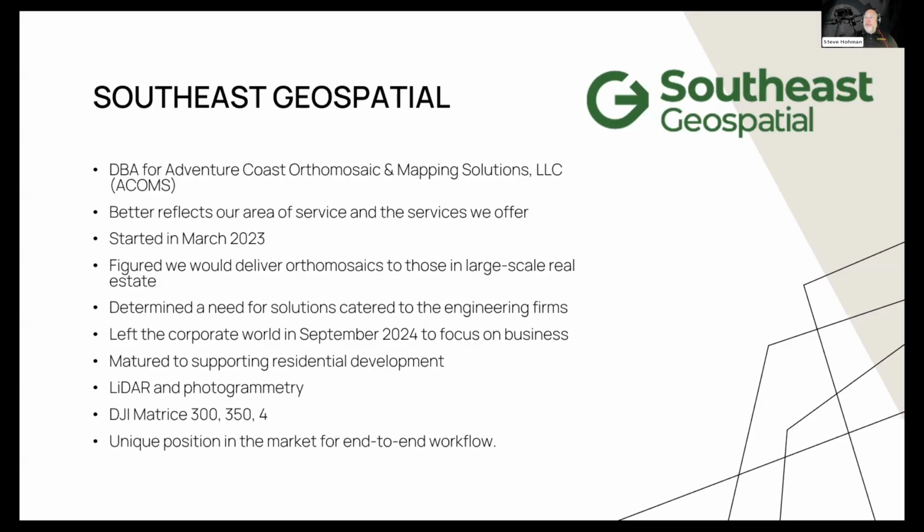That has to go through planning and zoning to make sure the use is going to be approved. We start with that with an orthomosaic. Then they have to go to engineering with the engineering firm. We support the engineering firm with our LiDAR deliverables and topographies through vegetation and everything, on a much faster basis than the traditional total station or using GNSS to get those measurements.